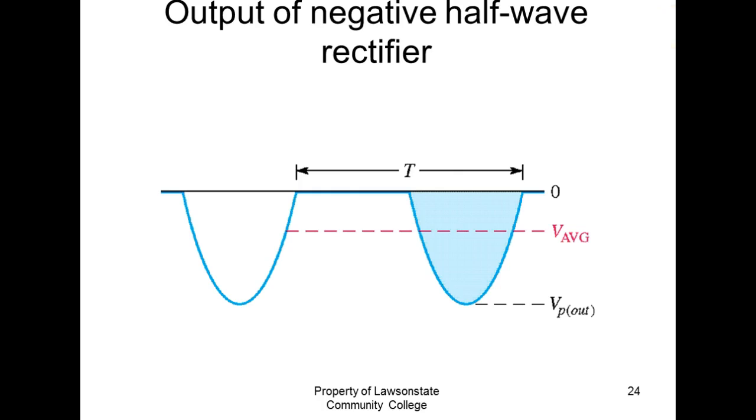Specification, setting up the VI characteristic curve for a diode. So we're not going to use an oscilloscope tonight. We'll use a meter, and we'll modify the program. Everybody got those lab books? We'll have to look and see how we're going to modify that circuit a little bit because of the range of our power supply.